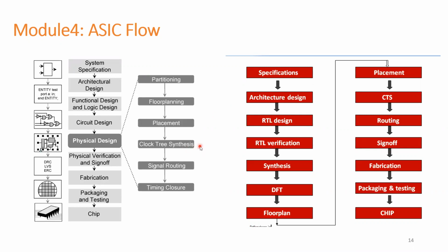In clock tree synthesis is the process of building clock from clock source to all the sink pins of the flops. We will have to build the clock tree in such a way that latency should be less, skew should be less, and the setup and hold timing should be within limits. So we should be able to close it in coming stages. So the clock network should be robust basically. So once CTS is done, we will route the signals.